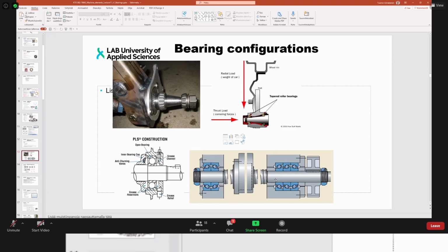Is it added only when needed or constantly? If the lubrication is done with oil, it's usually constant, or at least intermittent. So there is a pulse every maybe 15 minutes when oil is fed, or then it's a constant spray or constant drops of oil onto the bearing.